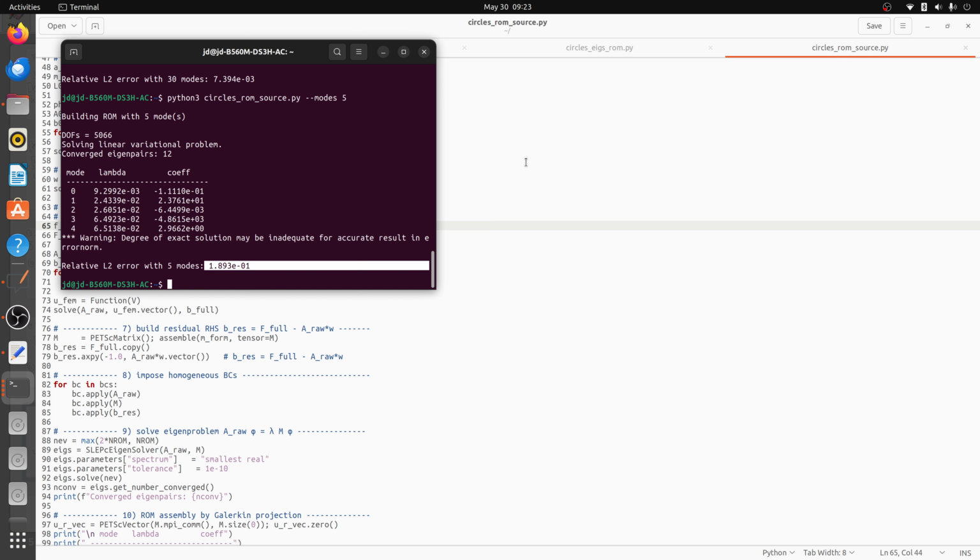So we are just creating a set of global vectors which are orthogonal to each other, and we can represent them as trial and test functions, and just projecting onto those functions will give us a reduced order model, right? So that's really the idea, and this is where I end this bunch of videos, and in the next bunch of videos we'll look at the Navier-Stokes equations.